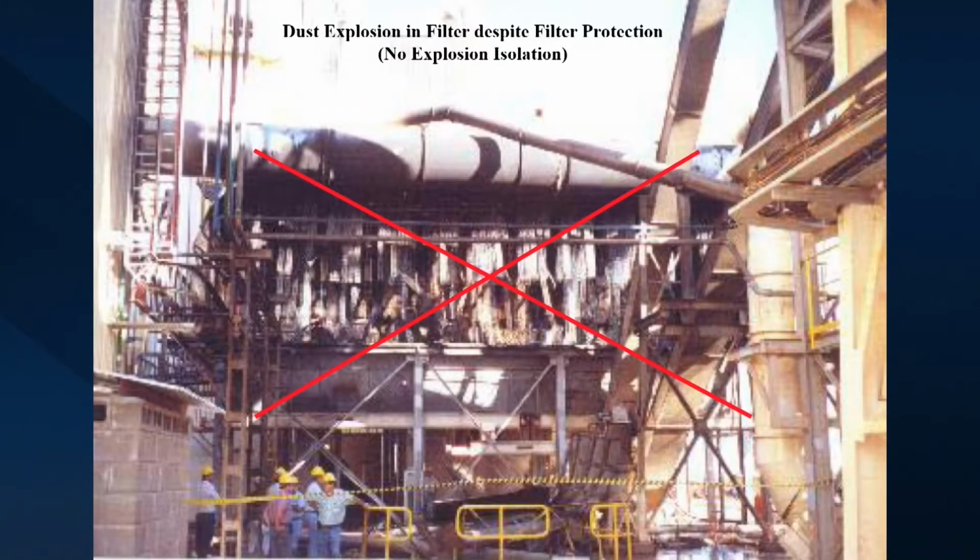We did have explosion isolation, and the explosion didn't start in the filter, but ran from another volume into the filter. And easily you can get much, much higher pressure than if the explosion accelerates into the filter. As I mentioned before, a typical explosion, if we had a dust cloud in here and we ignite it, has a flame speed of 5 to 10 meters per second.